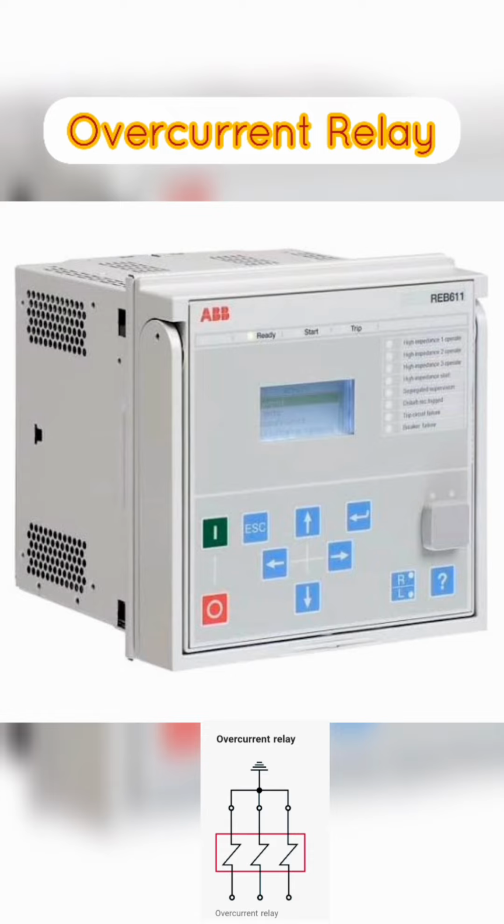Next we learn about overcurrent relay symbols. The symbol for an overcurrent relay is a rectangular box with diagonal lines passing through it, and a perpendicular line connected to the top or bottom of the box, depending on the type of relay. The diagonal lines represent the current flowing through the relay, while the perpendicular line represents the trip mechanism that trips the circuit breaker when the current exceeds a certain level.